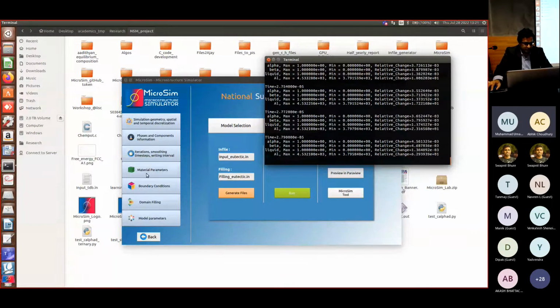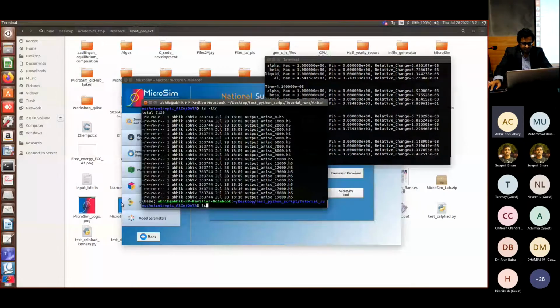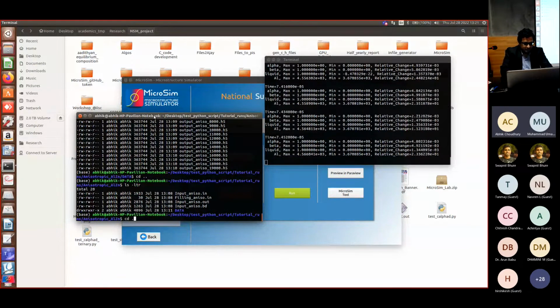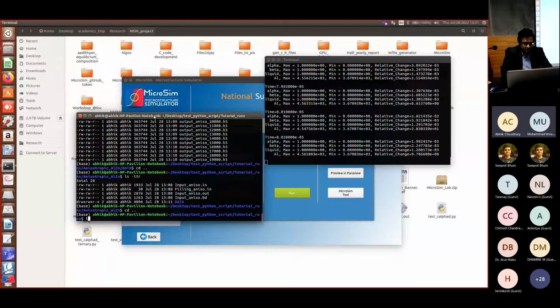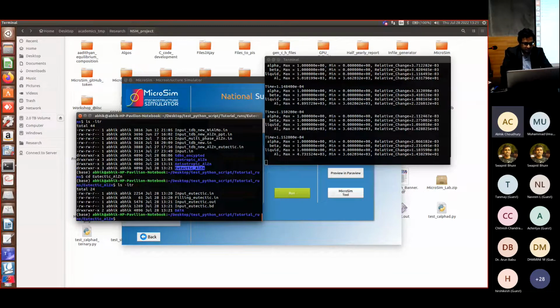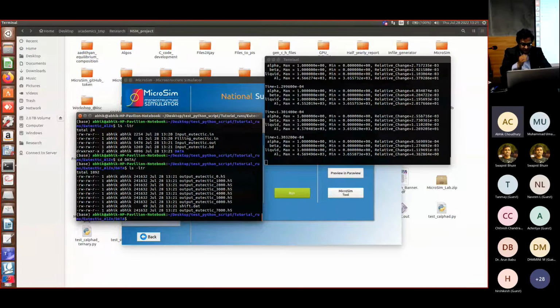And again, as before, we can go back and check what is happening. So we were doing it here. So you see a new folder is getting created, eutectic aluminum zinc. So CD data, right? So you see these files are getting written, and there is a new file that gets written down, which is shift.dat. This keeps a record of how much time you have shifted.